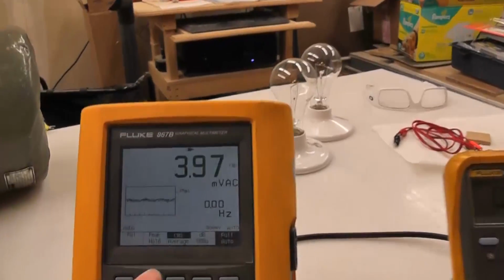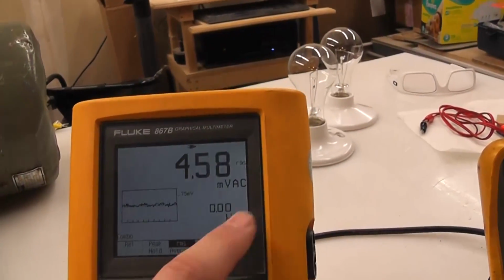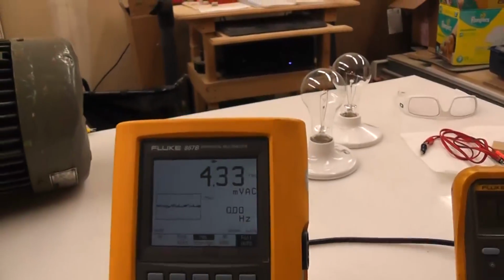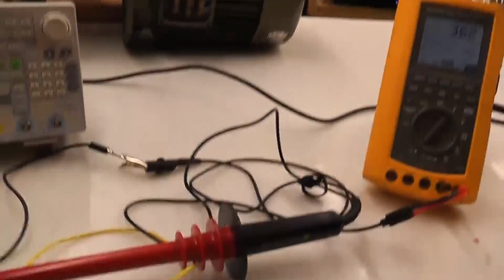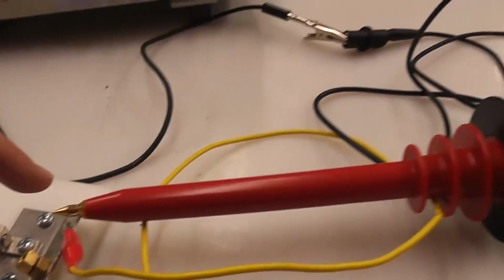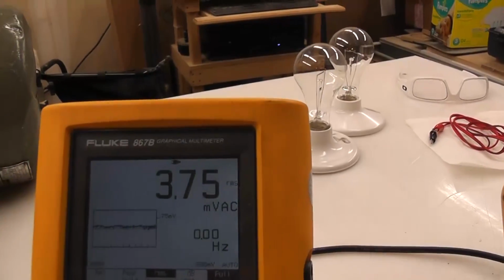So we'll be able to see the frequency on this. This is not as good as my scope, obviously. This is just a scope meter, but it'll do. Now the probe is just touching on the spark gap, and that's good enough. You have to multiply whatever you see here by 1,000 because it's a 1,000 to 1 probe. So keep that in mind.